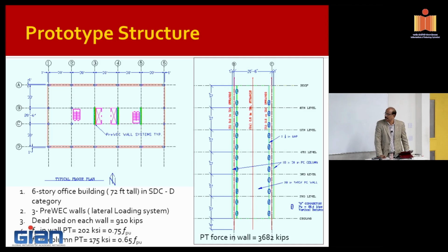This particular building was designed by a professional designer in the seismic region. She designed this structure for a location in Los Angeles, and she chose to use a seismic moment frame, specifically a hybrid connection, going in one direction. If you look in this direction, every frame here is a moment frame. So in this particular loading direction, these frames were supposed to take the load.